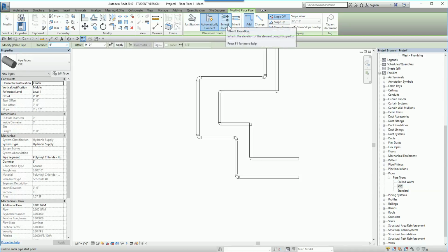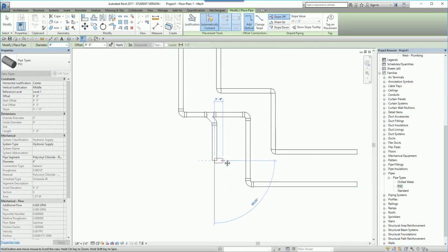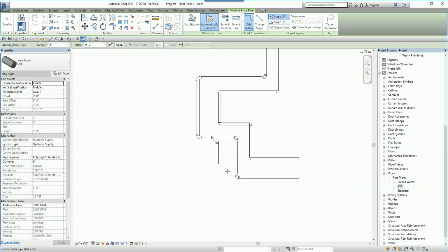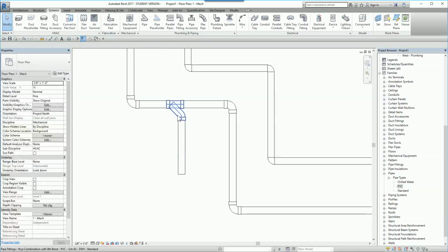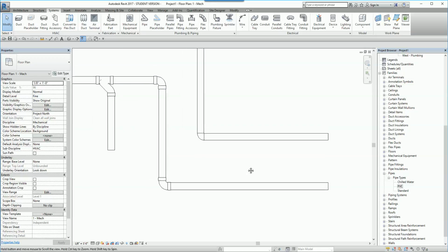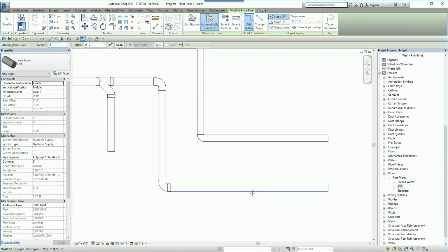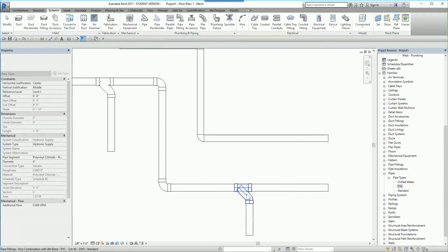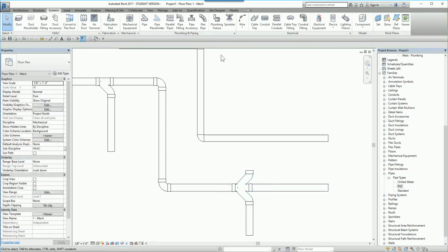Now when we do connections, one of the features that Revit has is that you can inherit elevation and inherit size. You can enable that so that when you connect any pipe to another one, it will automatically inherit whatever fitting information you're doing. And you see it took everything from the other one. Now on the fittings that we chose, I said the Y with 1/8 bend, that's basically what it is. In the previous video, we did the same thing here. See, it automatically disables this.